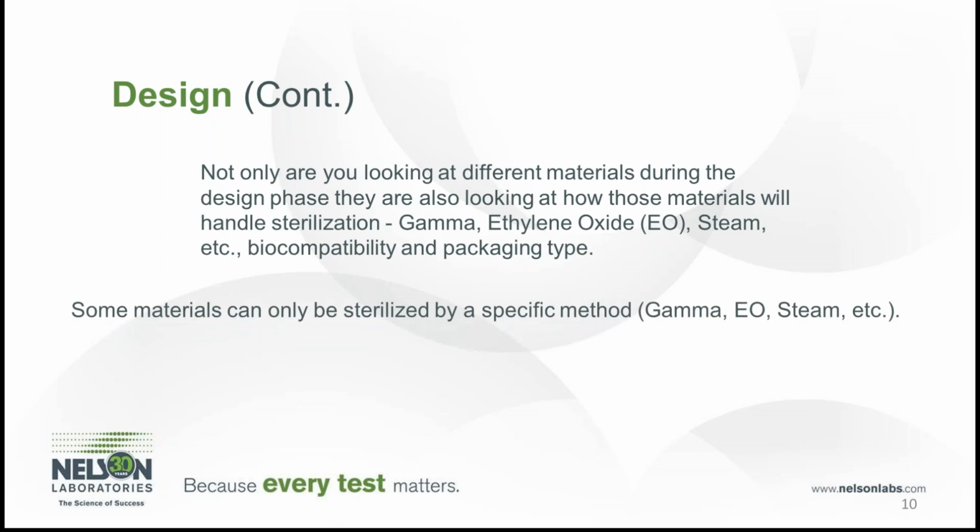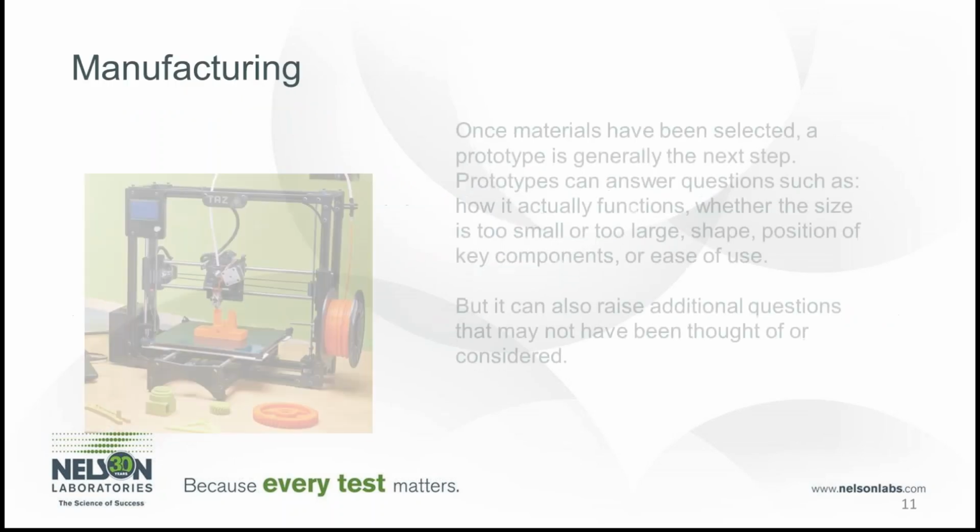Some materials can only be sterilized by a specific method, so by selecting a material, you can actually find yourself cornered into a specific sterilization method, which in some cases may not work for your product, your process, your intent, the operation, etc. And so you may need to look at readjusting what the materials are to get into a different sterilization so that it ends up working for you and your process.